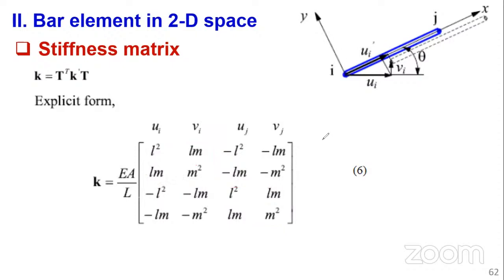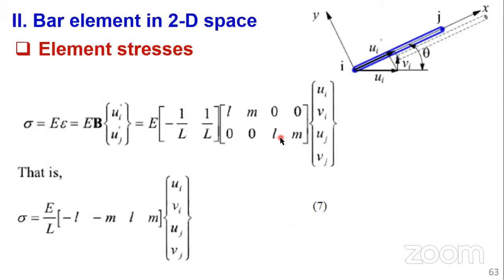And that's the equation that you use to transform from the local coordinate system to the global coordinate system. Of course, from that point, everything else goes the same way as the procedures that we have been following. Once we assemble the stiffness matrix, we proceed in the same manner. You introduce the boundary conditions, you solve the equations to obtain the unknown quantities, deformations, maybe forces, and then you can also start recovering derived quantities like the stresses.